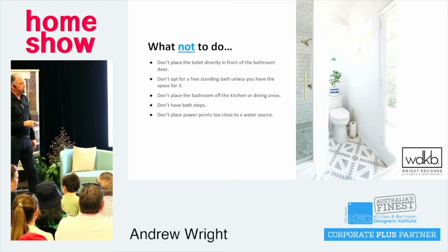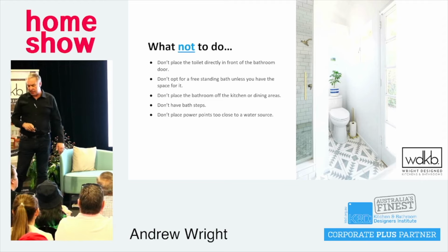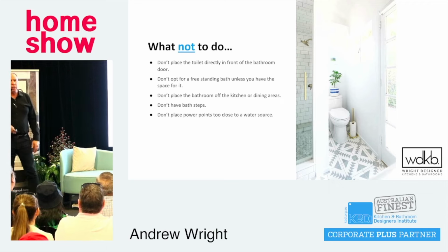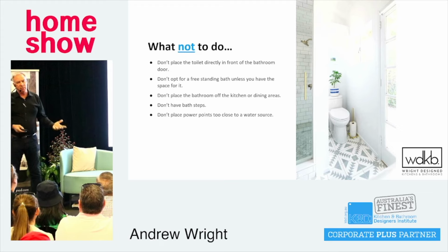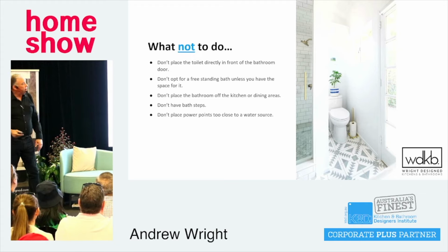Don't have steps in front of baths. That's gone. I still occasionally get people that want to suggest having a step in front of a bath. It makes getting out of the bath with wet, soapy feet, wet skin, pretty dangerous, particularly for an older person. If you have a freestanding bath, I'll talk about this in the next couple of slides. If you have a freestanding bath, make sure you've got enough space for it.